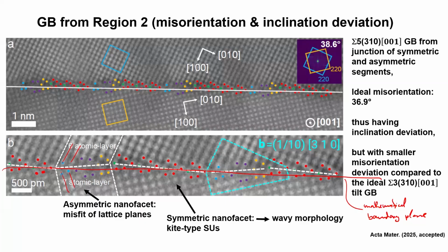So the Burgers vector of this secondary grain boundary dislocation will be a Burgers vector which doesn't fit to any of the two lattices. This dislocation-based description of grain boundary structures is exactly equivalent to the structural units description. You can either say there is a new motif, a new structural unit introduced, or you could also say there is a secondary grain boundary dislocation introduced. The meaning is exactly the same.